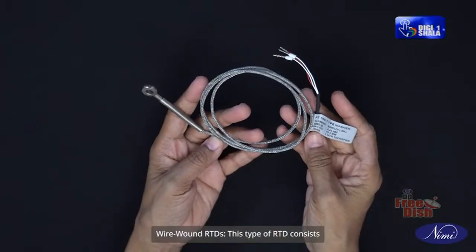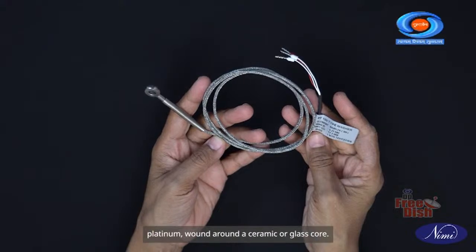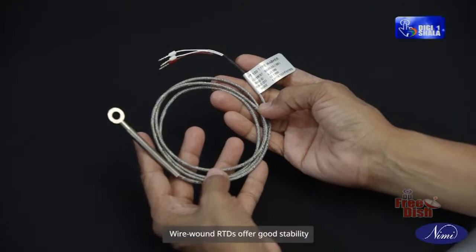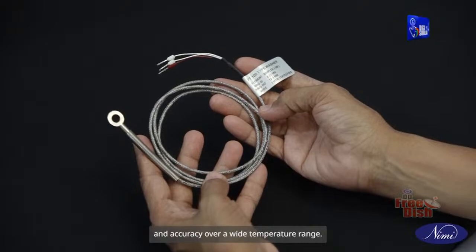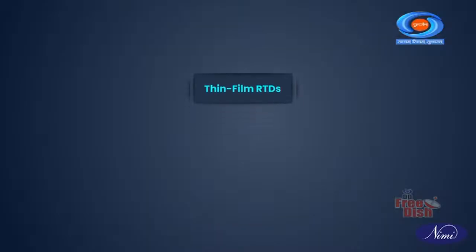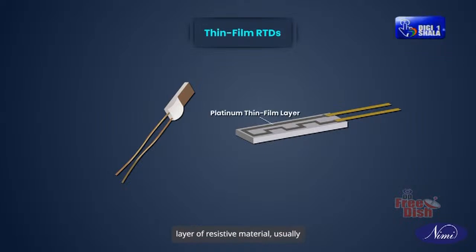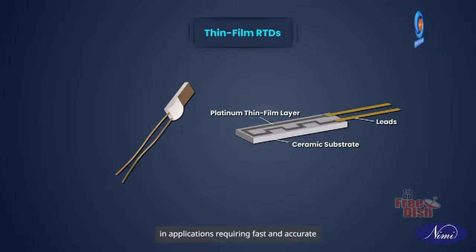Wire-wound RTDs. This type of RTD consists of a coil of fine wire, typically made of platinum, wound around a ceramic or glass core. Wire-wound RTDs offer good stability and accuracy over a wide temperature range. Thin film RTDs. Thin film RTDs use a thin layer of resistive material, usually platinum, deposited onto a ceramic substrate. Thin film RTDs are commonly used in applications requiring fast and accurate temperature measurement.